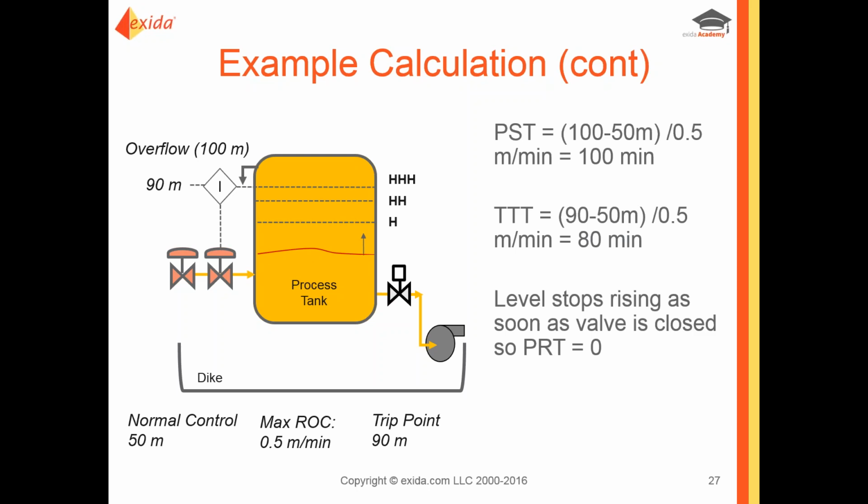In this case, the SIF action is simply turning off the flow valve, which we are going to say is essentially a process response time of 0, almost an instantaneous valve closure. And the site has determined that they want a minimum of a 10-minute safety margin on this particular scenario. So there was a judgment decision made in what that safety margin ought to be.